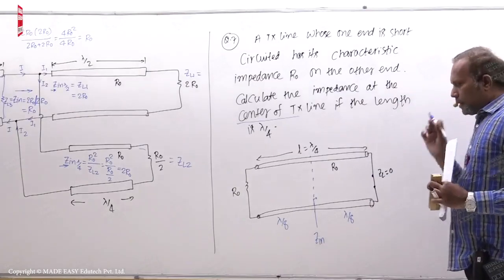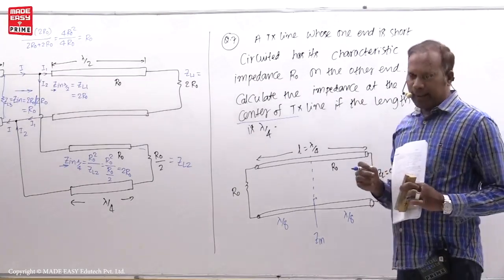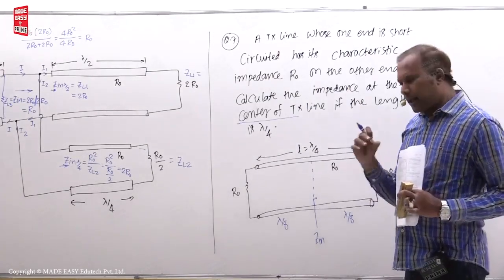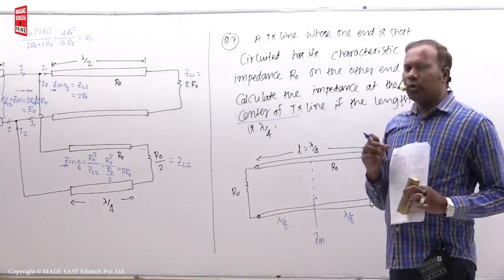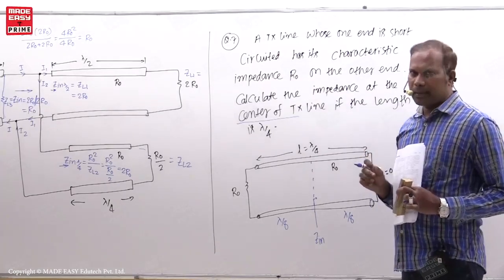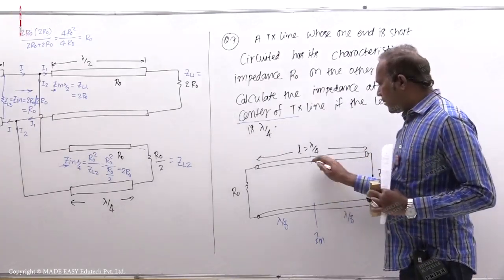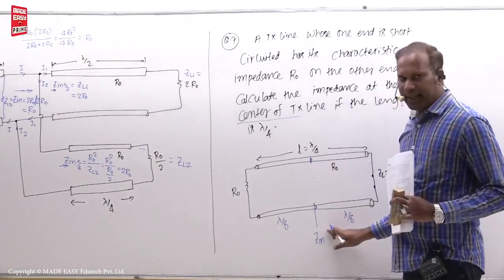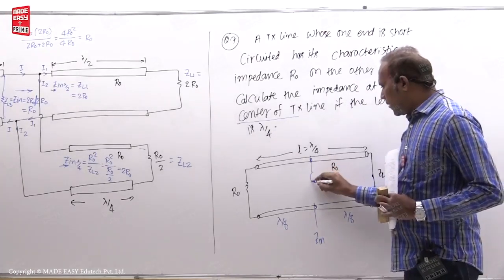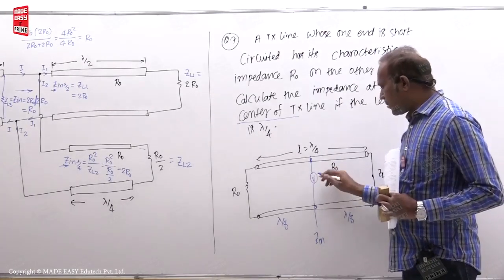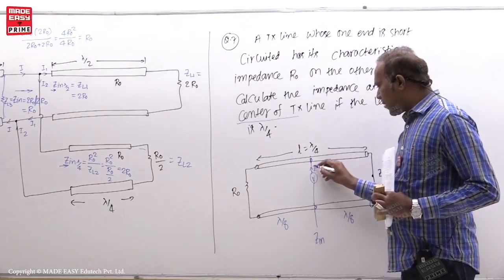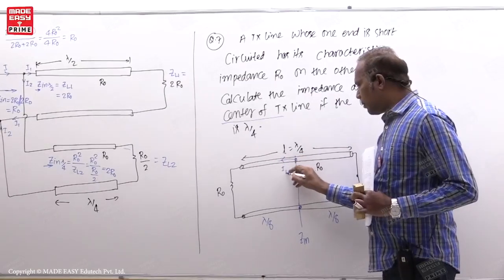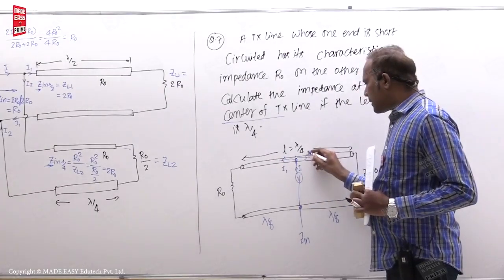Now what to do? It is like network theory. In network theory, that means electrical circuits and networks. In electrical circuits and networks, how to find Thevenin impedance and Norton impedance? For example, at these ends, these are open ends, at these ends you want impedance. Then what we do, we connect some voltage source at these ends, then this voltage source generates I current, then that I current is split as I1 and split as I2.